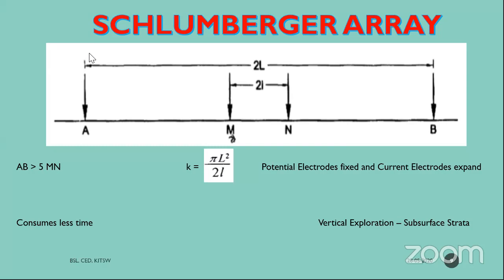1D or vertical electrical sounding is used to give vertical exploration only. It can give a complete picture of soil status in the y-axis, like depth. So you were making a borehole, and again you were doing a vertical ERT. And if you want a lateral image, like 2D imaging, without using this, the answer is no.